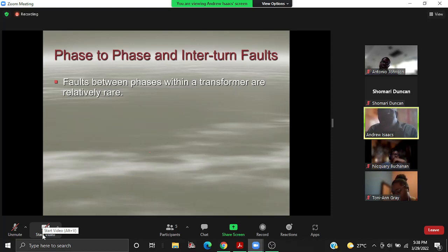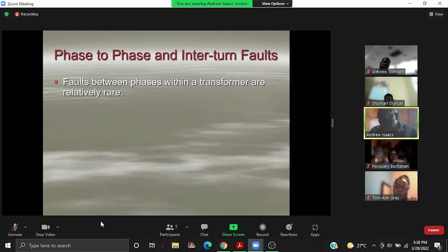So if it is then exposed to all these external shocks, which although created electrically, have a mechanical impact, what you can end up doing is to loosen those core bolts. And it is in those circumstances that you're going to end up having winding faults. Because otherwise, there are no moving parts in a transformer that we all know.